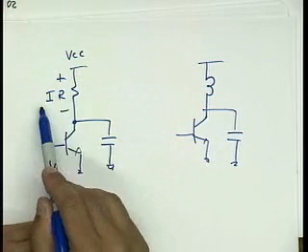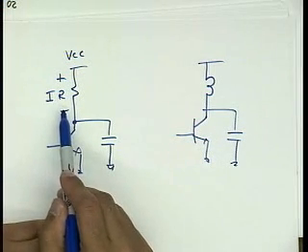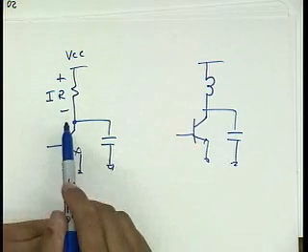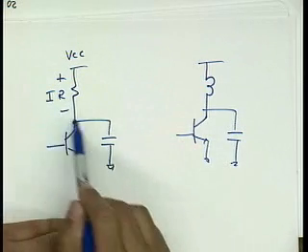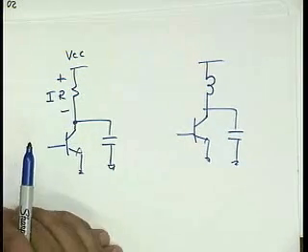So that more or less limits how large I can make this current, or vice versa, how large I can make this resistance. And of course, we also know that this resistance produces a time constant with this capacitor, and that also limits the bandwidth.